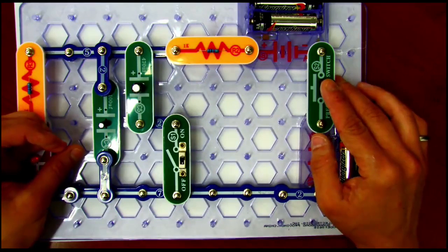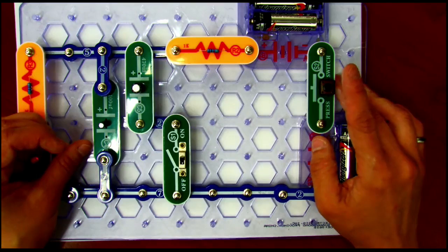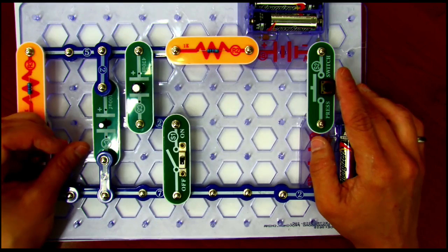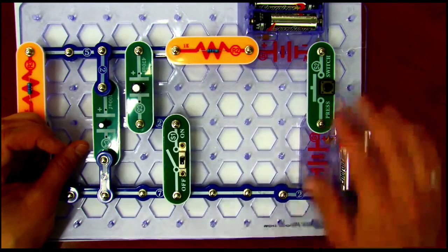So it's lit up. If I unclick the switch, I'm going to use the energy from the capacitors. You see it takes a little while longer, actually quite a bit longer, for the light to completely go out because we've added a big fat 470 microfarad capacitor in there.